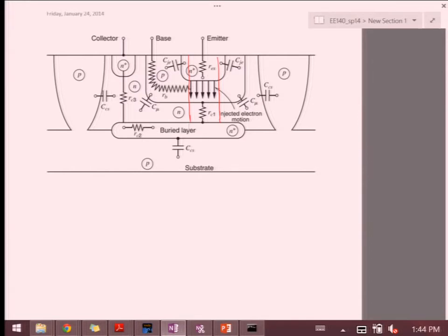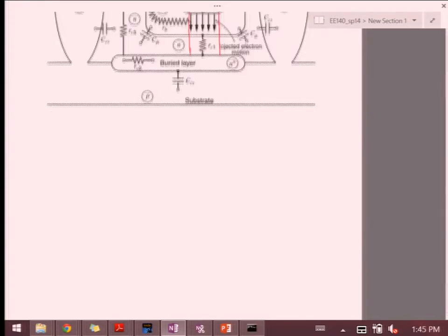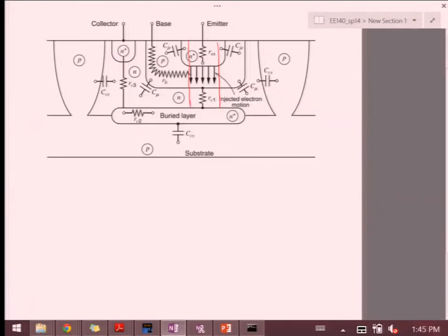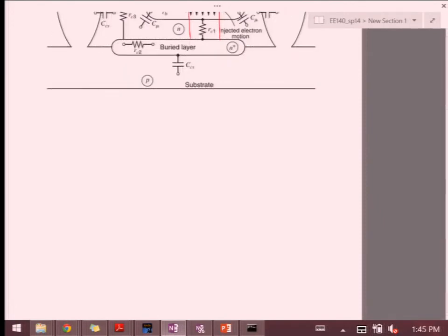But as you start moving electrons faster, as with small signal, you apply an AC source of very small amplitude and look at electron fluctuations, which means your current at the output. At some frequency, you may start noticing some of the effects, especially the parasitic capacitance effects. So if we take a look at how I can map all these other things into small signal, this is a more complete model.